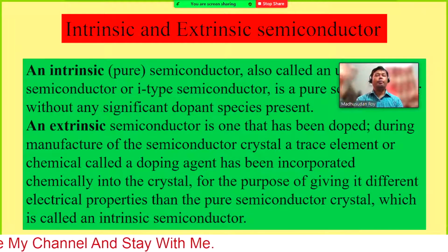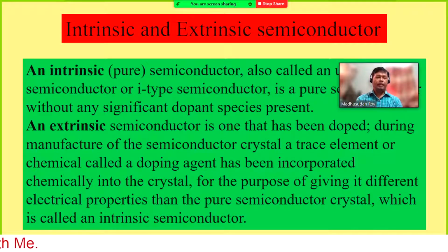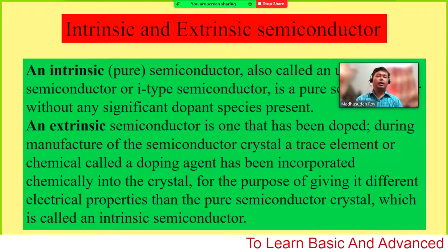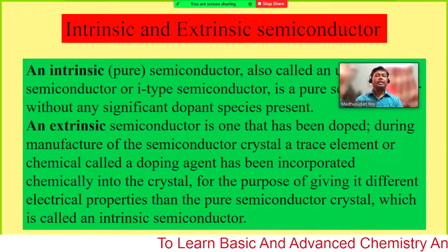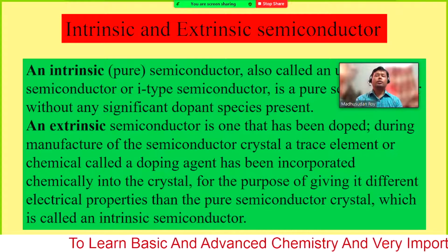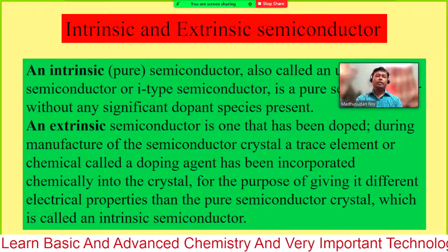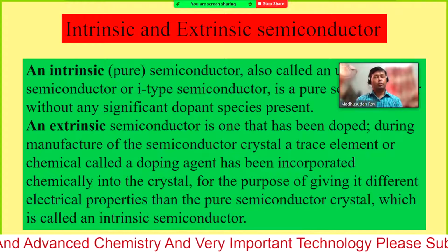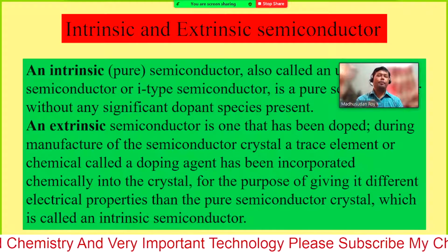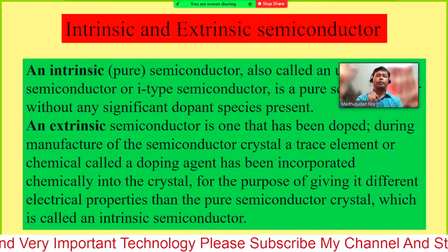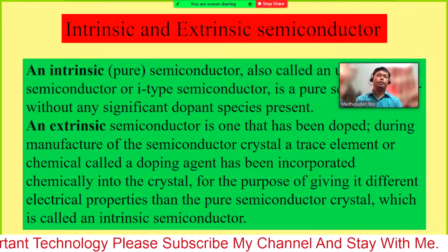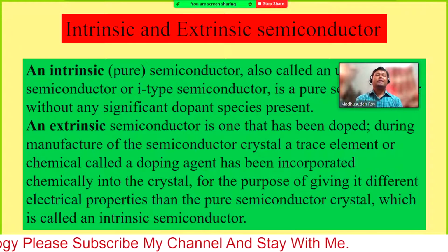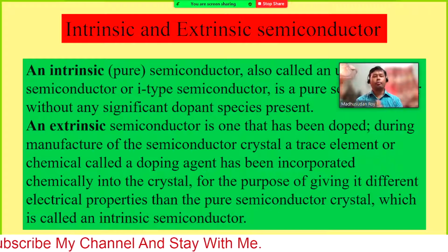However, if you have a very good semiconducting material with proper dopant and controlled ratio, that means what exactly you need, in that case the extrinsic semiconductor can be compared to a metal because its conductivity increases quite a lot. Sometimes if you add a trace amount of dopant, the conductivity increases from 1000 to a million times or even more.